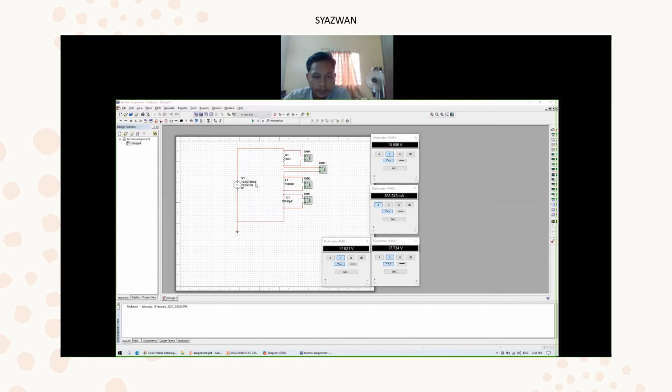and frequency 79.577 Hz. Okay, how to get voltage output? Firstly, the step is we must connect the multimeter to each component, at the R1, L1, and C1. Okay, how to get the current output? To get the current output, we must also put the multimeter here and connect to the line. Also, we remove this line.